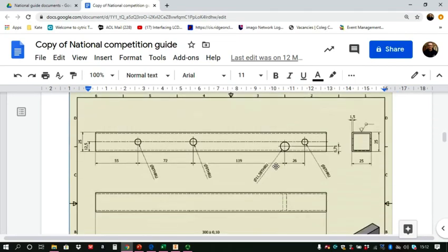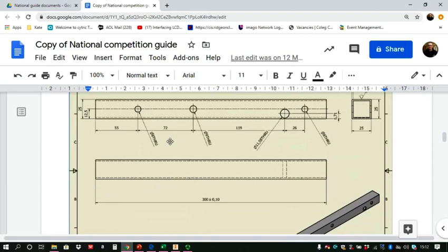So we've improved it ever so slightly, and this is one option. It now says diameter 8 through. Through, yep, we now know that goes through. It's box section. Does it go through one side? Does it go through two? Okay, we've got a height though, 12.5.